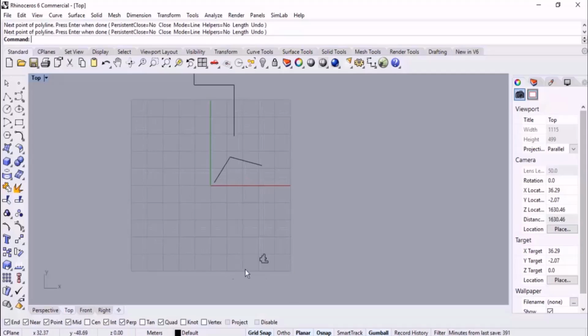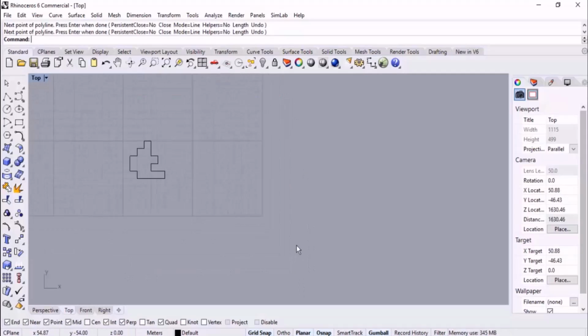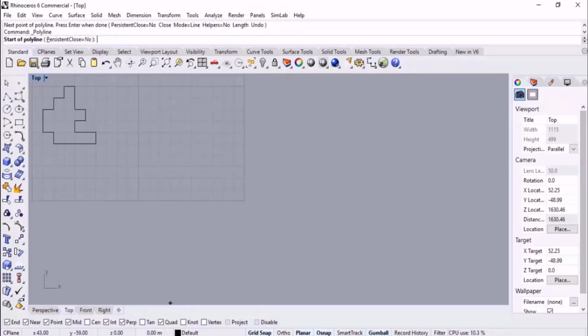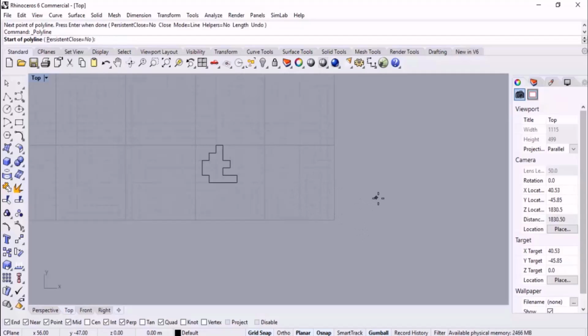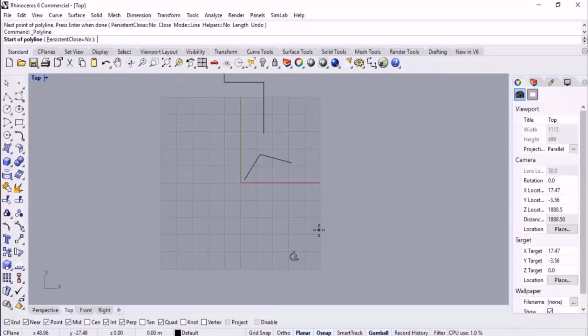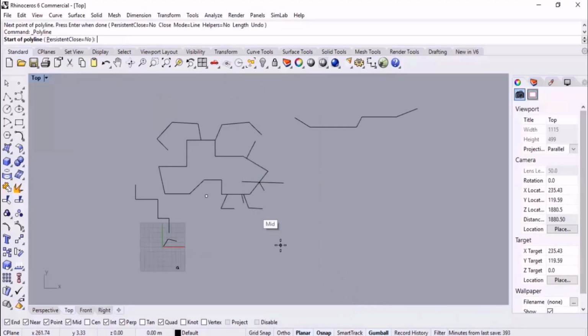What about the points? As I told you before, we got an infinite array of lines here, which are endless. However, only a defined region of it is visible in the viewport. We got the grid lines everywhere in the viewport, but graphically it is not visible. However, we can extend the visible region of the grid lines, but it is not necessary. So even when the grid lines are not visible in the viewport, we should know that it covers the whole viewport and the plane is infinite, and we can deactivate it if we don't want to constrain the marker to the crossing points.